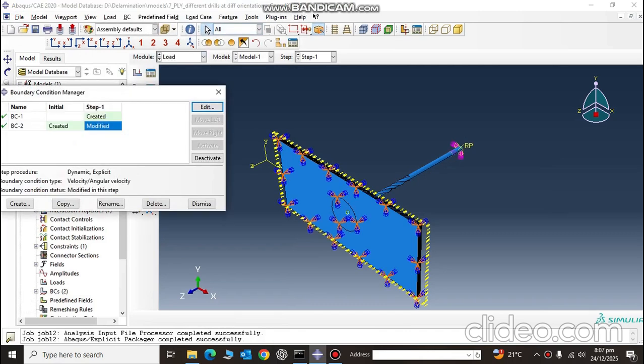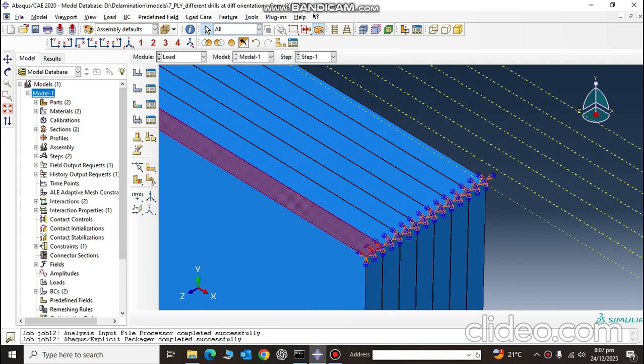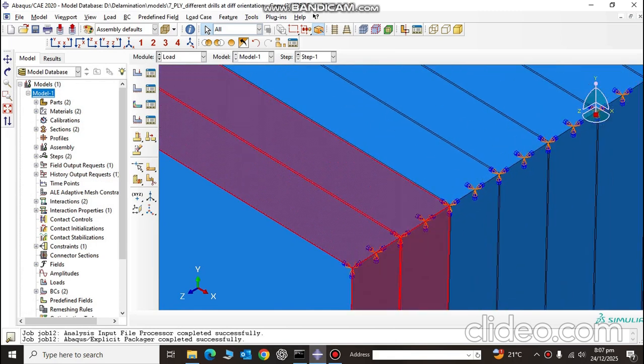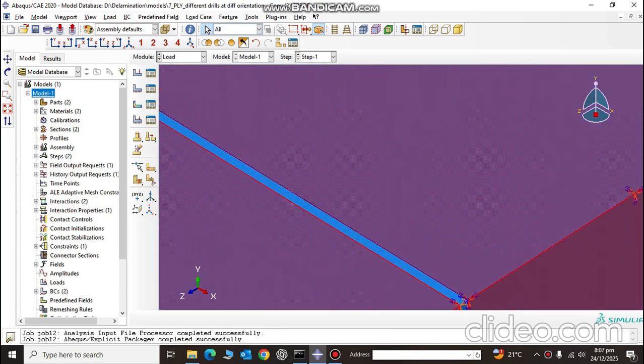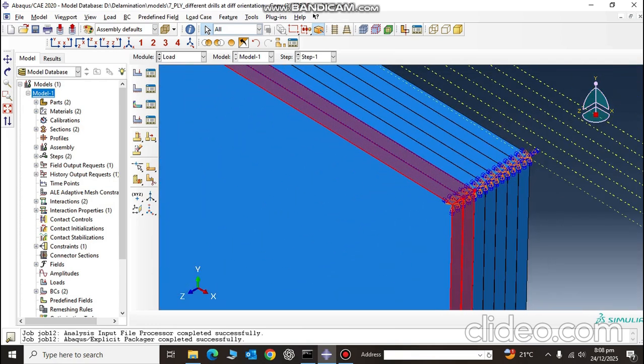that for example, if this is my boundary condition, and you select the middle one, make sure both the edges are below. For example, now both edges are below, now press shift and then click, then it will get selected. But if somehow you click the edge and then you click the middle part, this causes error. So you need to be very careful when you are selecting the boundary condition.